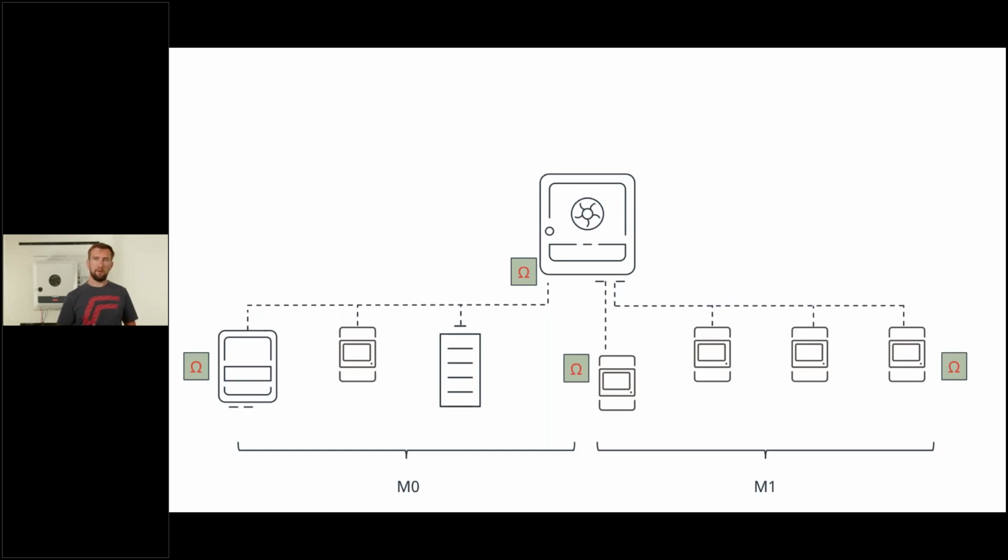They're in constant communication with each other. And so we reduce that number by 1. The battery counts, if you like, for 2 smart meters or for an ohm pilot and a smart meter. So we make sure we only add a maximum of 2 other participants to that Modbus line.